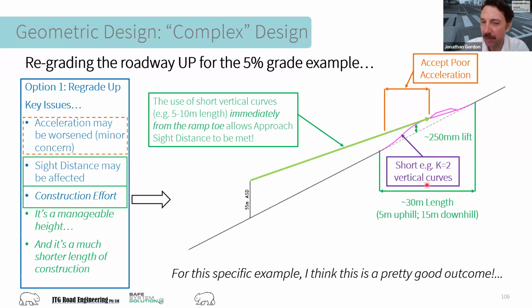If you start going a little bit bigger than these, they come out at the wrong angle and start to block sight distance. But short curves actually may work for you and may be a better solution than medium sight value curves. And in terms of costs, it might actually be an acceptable outcome that is superior, particularly in terms of cost, to one that adopted desirable approach sight distance values from the guides.